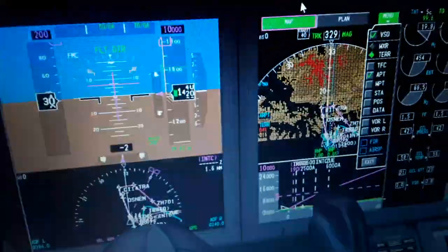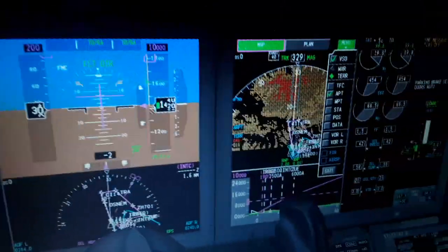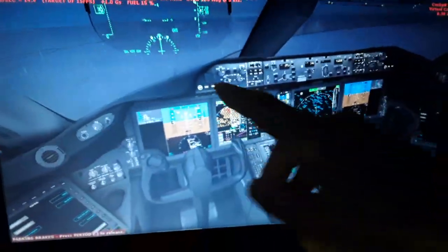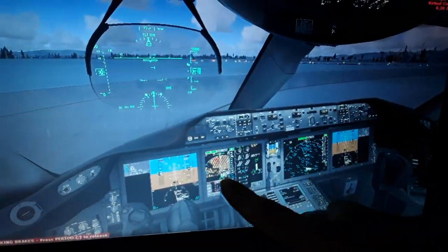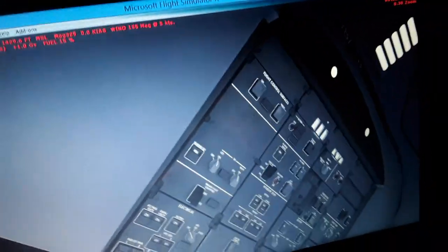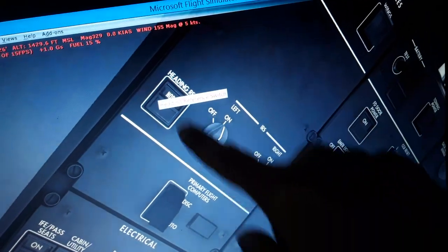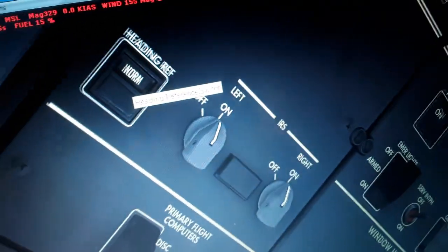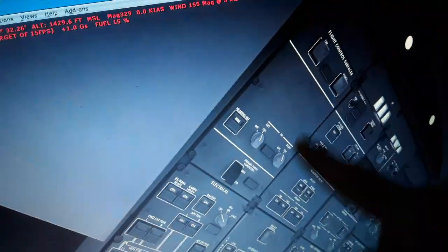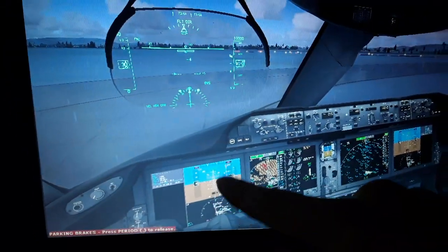All the data you see here from the pitot static and pitot dynamic, the airspeed, the altitude, the rate of climb descent, the laser gyroscopes for the laser gyroscopic acceleration, deceleration, magnetic north pole and geographic north pole, inertial navigation, GPS receivers. So all are contained in this air data computer. Here you see heading reference.